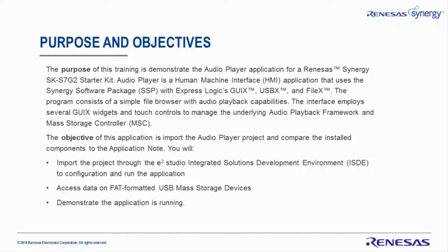The interface employs several GUIX widgets and touch controls to manage the underlying audio playback framework and the mass storage controller. The objective of this application is to import the audio player project and compare the installed components to the application note. You will import the project through the E² Studio Integrated Solutions Development Environment (ISDE) to configure and run the application. You'll access data on a FAT or FAT32 formatted USB mass storage device, and you'll demonstrate the application is running.